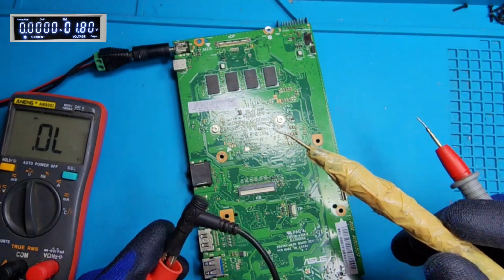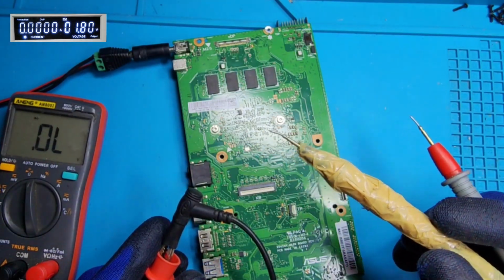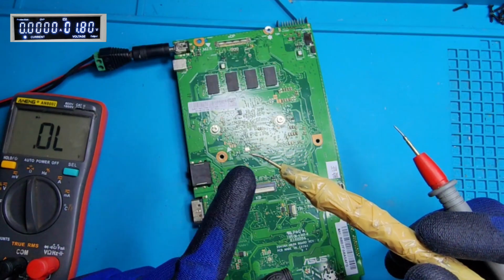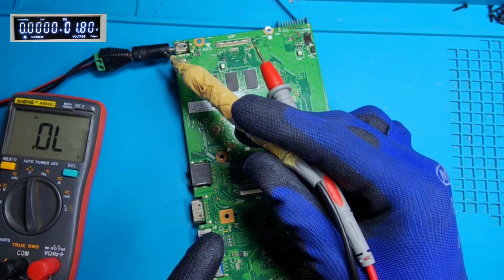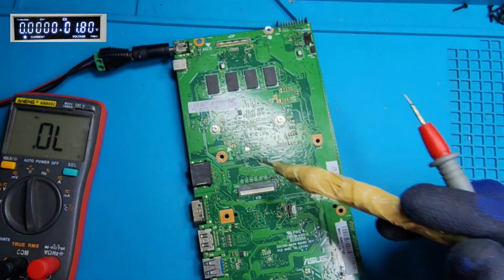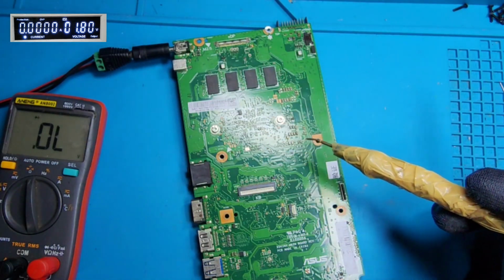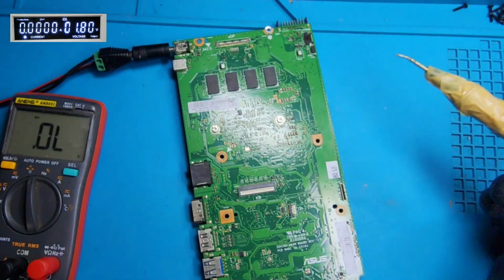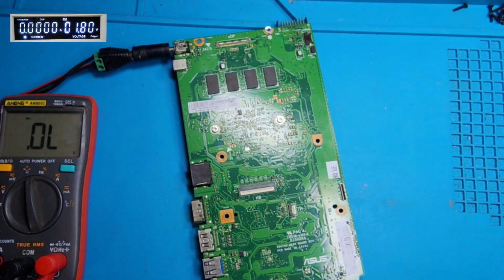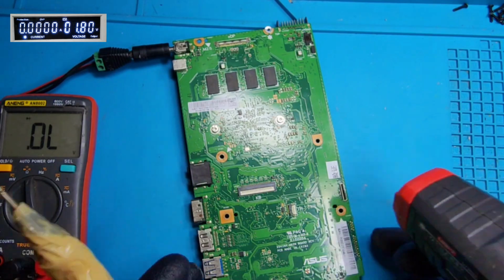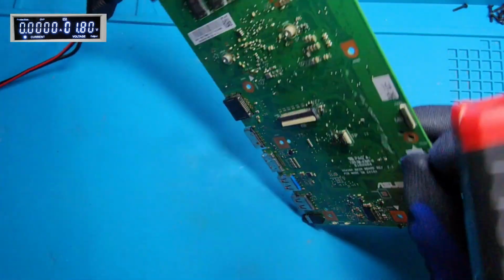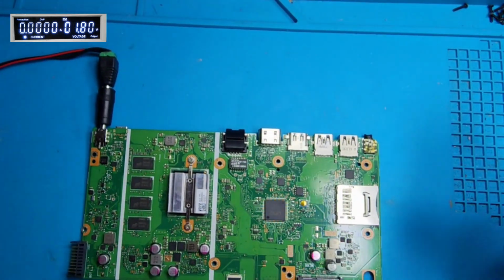So this probe is connected straight to the positive terminal of the DC power supply. So at this point you will get the positive voltage, and here we have the ground potential. So now I can touch it anywhere to inject the voltage into the motherboard. So it will be easy for us to inject voltage anywhere. Okay, where is my handy tool, which is this one here. So I can check the temperature reading when I inject the power.